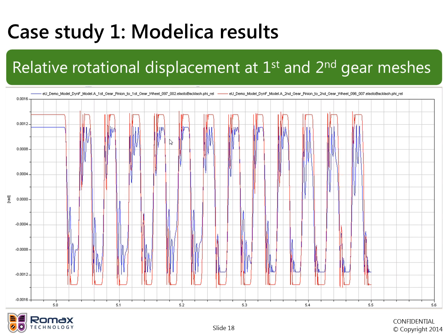So we could now go back, and with this model we could make changes to it. We could make changes to our clutch design, for instance, or flywheel design, changes to the engine excitation signal in an attempt to reduce this rattle behavior.